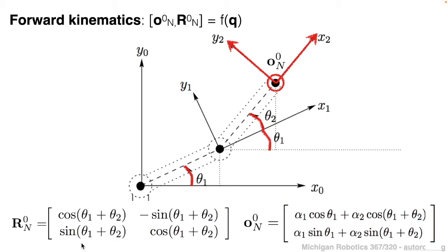And so I'll just point out that, again, the only variables that are needed to actually calculate both the orientation and also the translation are theta 1 and theta 2. In addition to that, we have alpha 1. And so we could think about the kinematic structure of our robot as also being needed as input, as part of this configuration queue. But really, if we have theta 1 and theta 2, if we know the joint configuration state, then you can perform forward kinematics.